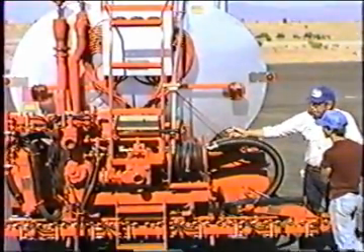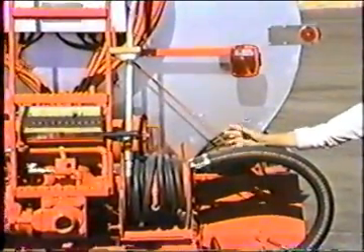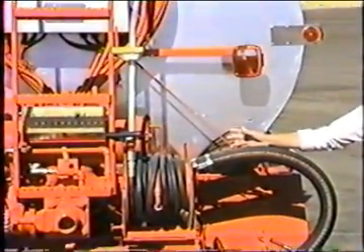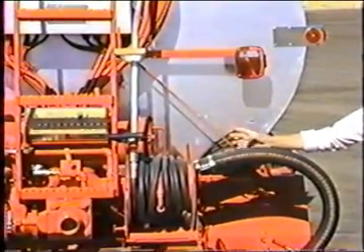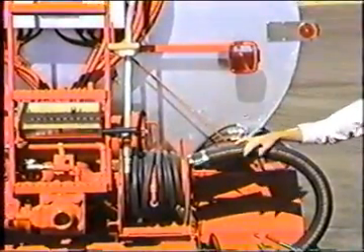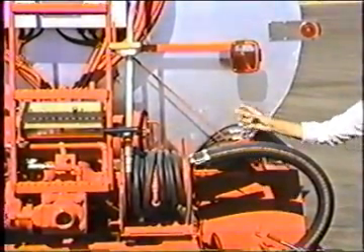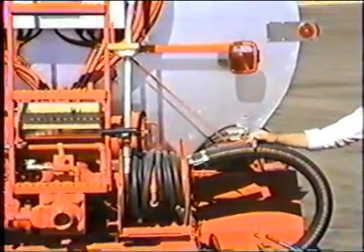It's not internal. A lot of asphalt distributors have an internal valve. This is not a true internal valve. True internal valves have problems in that they can be plugged up and you can't get them unplugged. This particular valve is mounted on the surface of the tank, right tight against the tank, so it gets the heat but doesn't have the plugging problems.